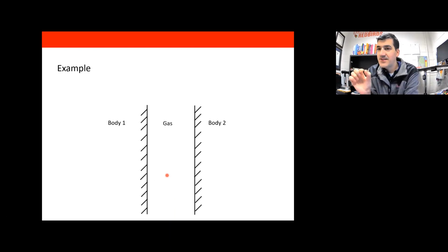But now think about your conduction heat transfer. It's L divided by kA. That's the resistance, right? So if L is really small, then you're reducing your thermal resistance from conduction.